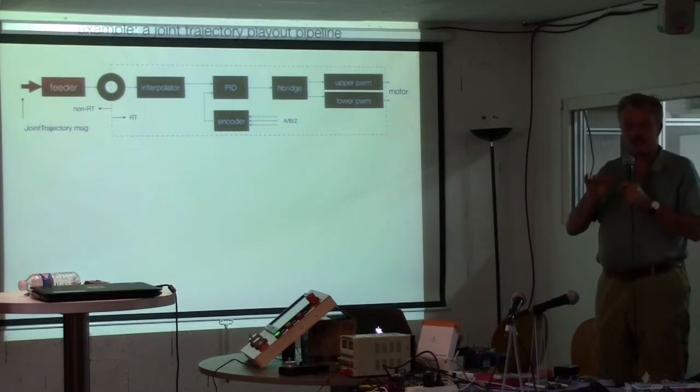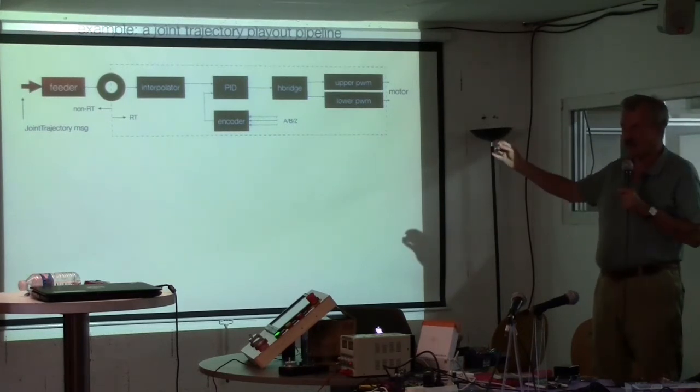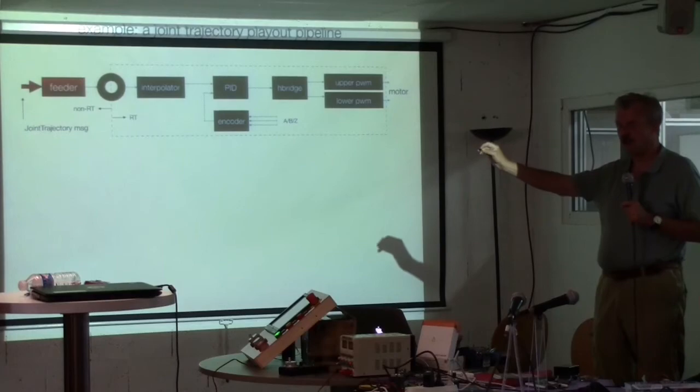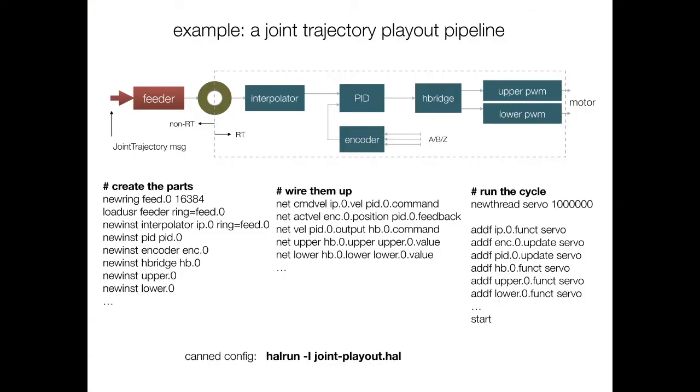Such a trajectory might have segments which are rather long, like a slow move over a long distance, so that might run for 20 seconds, and then it goes into a corner, which is just a very tiny arc, and then it again does a long move. So these segments are not equidistant in time, not equitimed, but they have different duration. These segments are attributed with time.